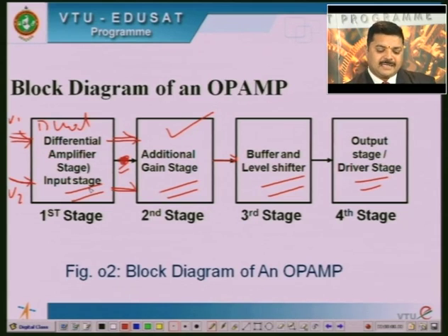V2, and it gives the voltages at 2 points, and those two voltages are given to the additional gain stage to increase the gain of the amplified signal. So to increase the gain of the amplified signal, we use an additional gain stage, which is also a dual input unbalanced output differential amplifier. It is used to provide additional gain to the output of the first stage.